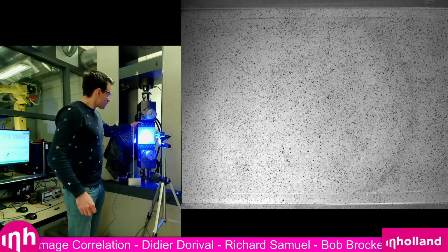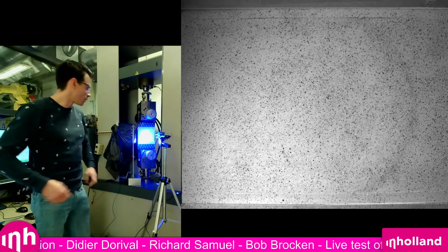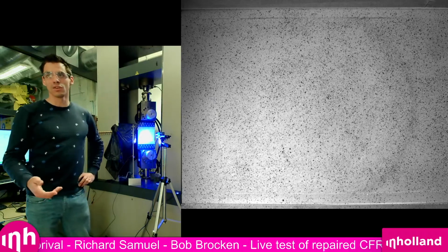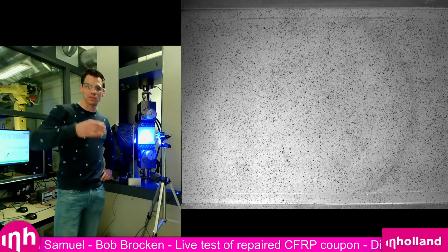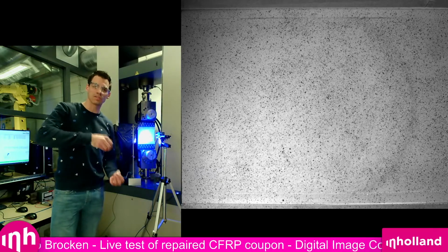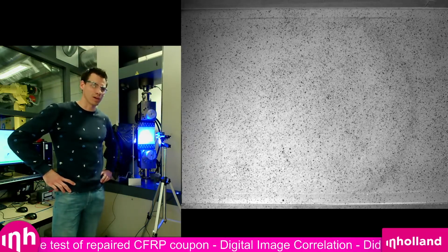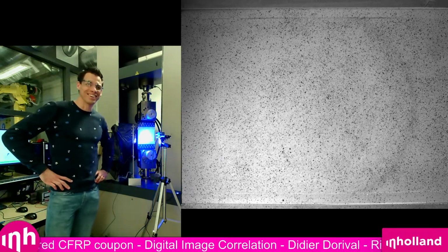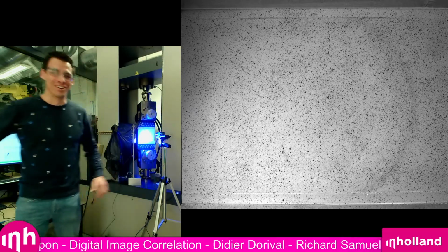The sample is clamped with a relatively high force, because depending on what sort of layup you choose and how well the repair has been designed and done, we'll get a result somewhere between 70 kilonewtons and 150 kilonewtons. But you have to imagine that the test bench has to clamp this sample with some sort of pinch grip, and in that way be able to resist pulling it out with 140 kilonewtons, or 14,000 kilos, about the weight of 7 cars. We also advise you to put your volume up a bit, because the bang is quite loud once it actually goes.